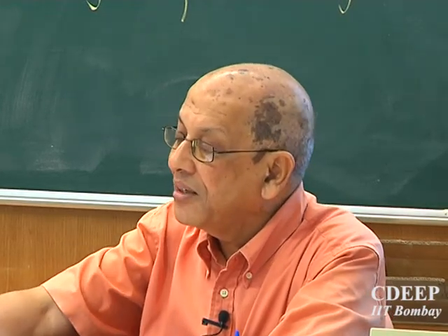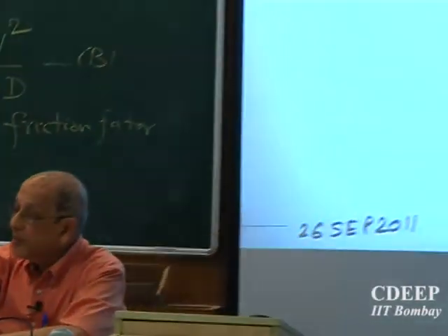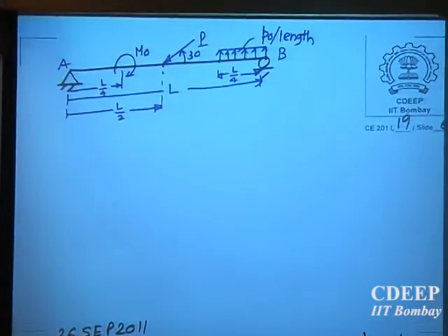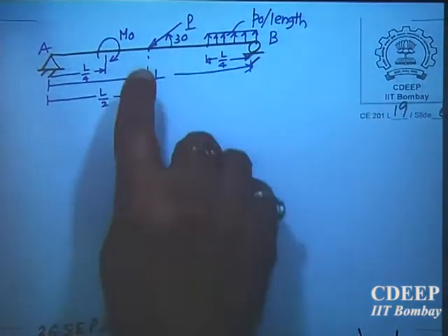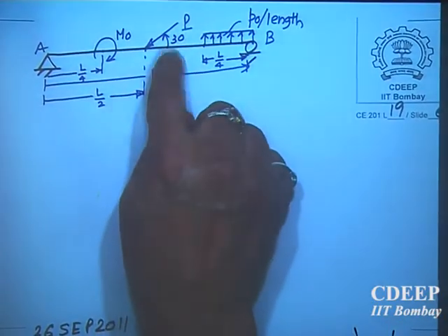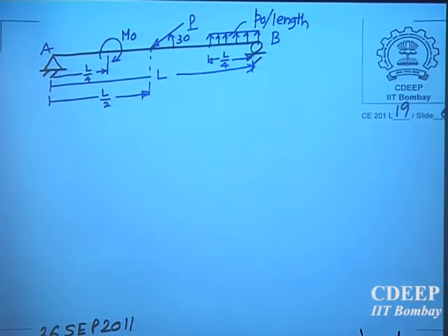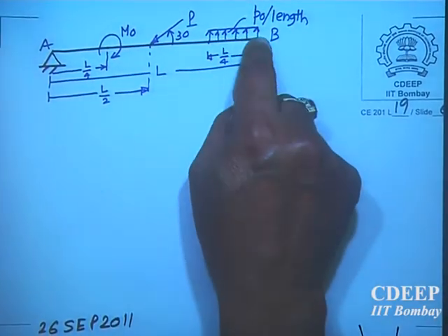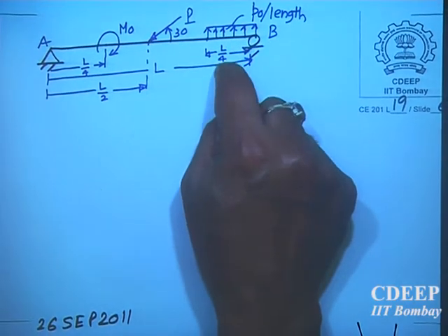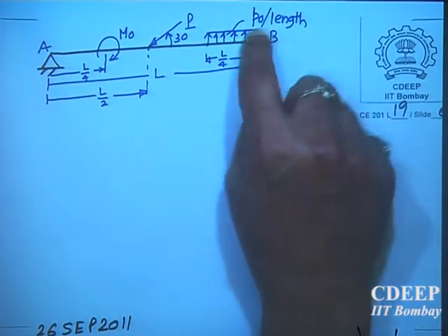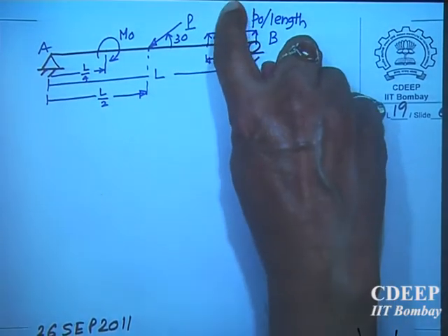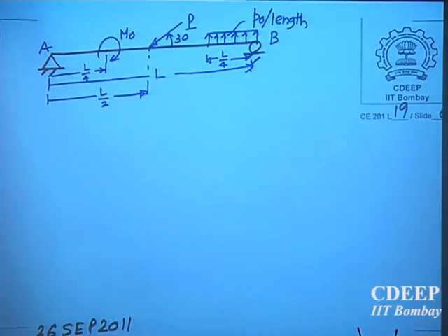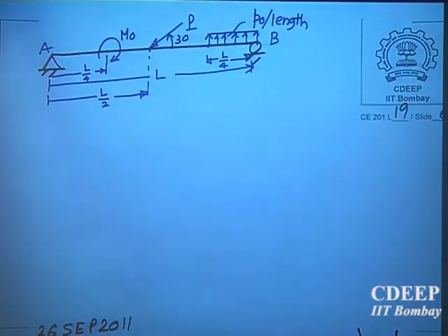That you can see. This can be split up into vertical and a horizontal force. The central one can be P cosine 30 and P sin 30, and this one will give you an equivalent load of P naught L by 4 upwards and applied at L by 8. Resultant of this. Now you can find out based upon this.